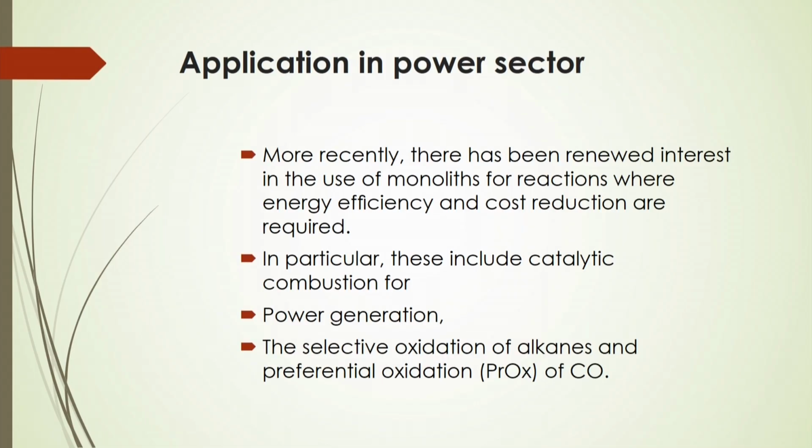Because their combustion will be catalytic, and generation of steam from water will also be one important aspect there. So, power generation, the selective oxidation of alkanes, and preferential oxidation of carbon monoxide, based on energy-efficient processes by monolithic reactors, are being applied in particular in this power sector. So, the applications are not only in the environment, but also in other chemical engineering processes, like Fischer-Tropsch synthesis, where gas-liquid-solid reactions are there to produce different types of hydrocarbons. So, there these monolithic catalytic reactors are important.